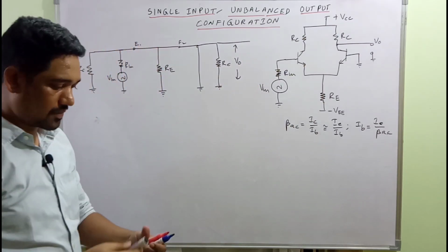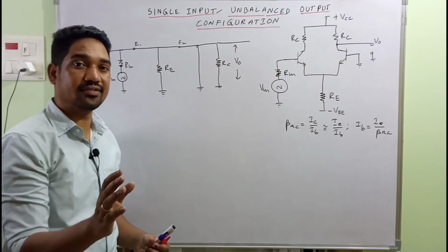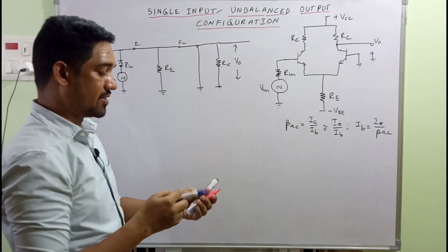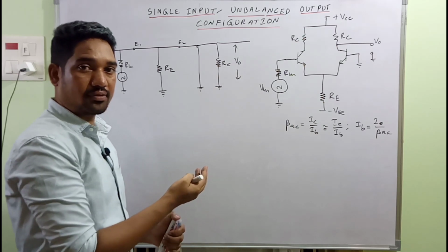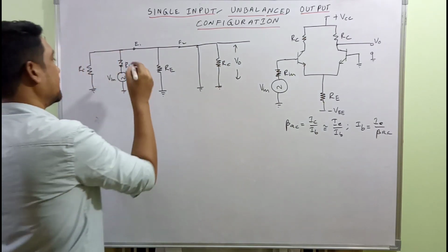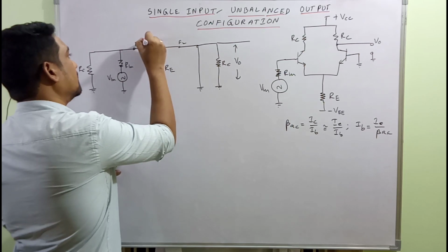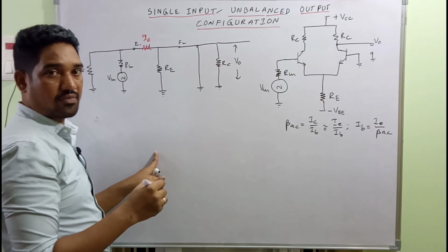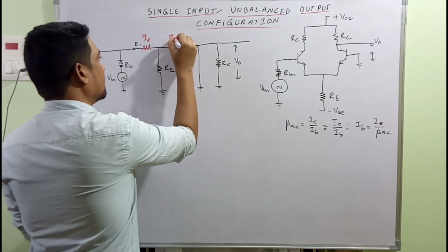In the AC equivalent, we cannot neglect the dynamic resistance of the emitter junction. It appears over here while we discuss AC. If the discussion is about AC inputs, the dynamic resistance of the emitter junction comes into the picture. Where is that emitter? Here, these are emitters. Make a note please. We have the resistance re, which is known as the dynamic resistance of the emitter junction, and another transistor, even that has re.